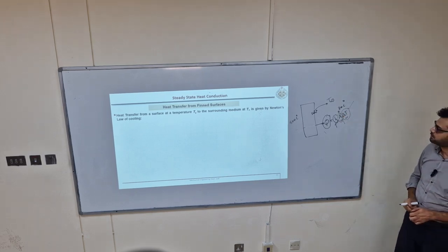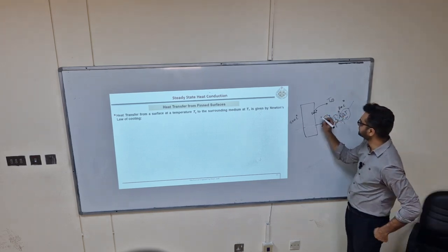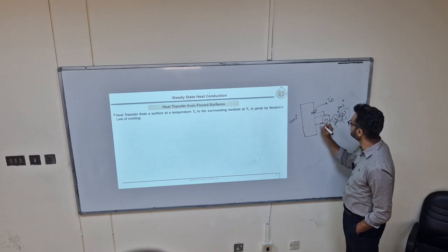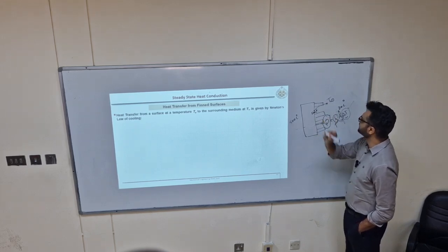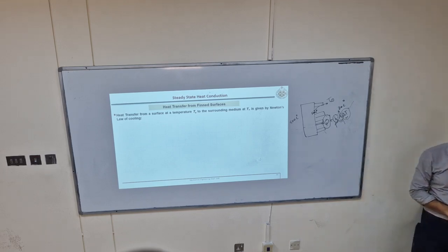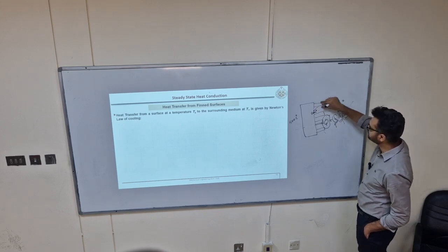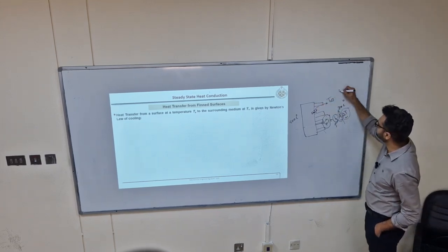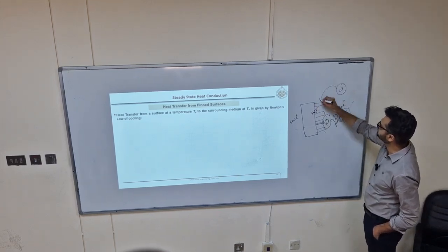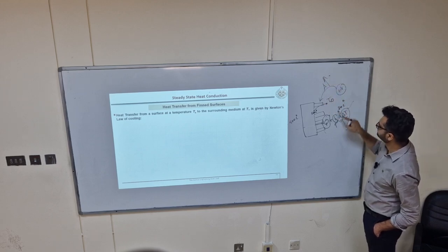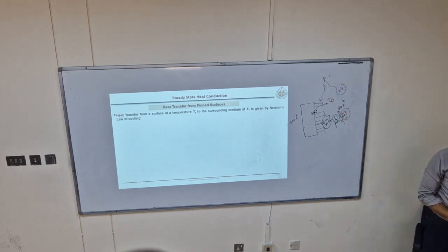The surface area through which heat is transferred. So on this surface, now if you increase the heat surface area like this, you install such extended surfaces. Extra material is attached. Extra material means now if you see in 3D, you have extra area of heat transfer. The same air is now coming in contact with a larger area. Right?